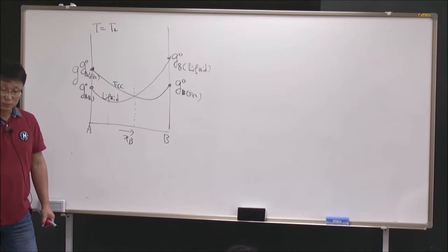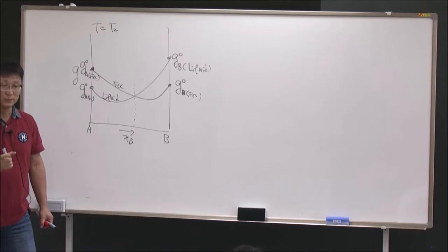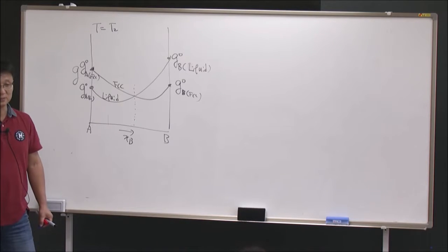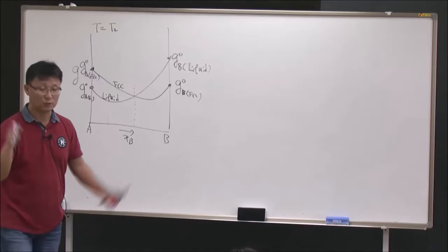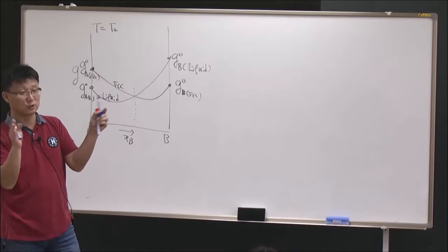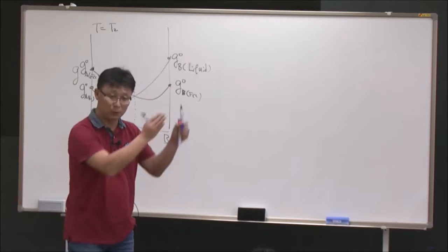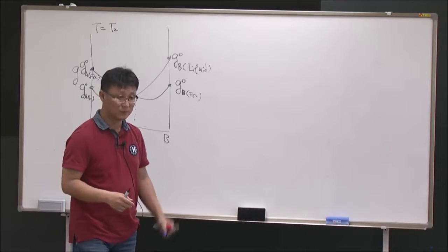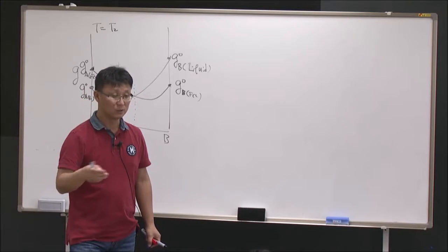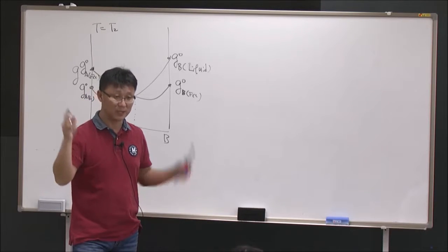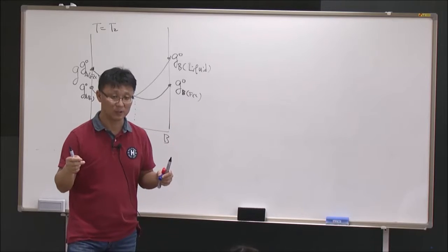That's what happens when we assume there's only a single phase possibility. Okay? But when you mix A and B together, if A and B don't actually make any solution, you can have pure A and pure B existing together, yeah? So we're going to learn later the so-called Gibbs phase rule to tell how many phases can exist at maximum in a given system, okay?